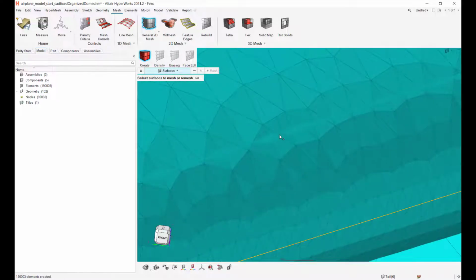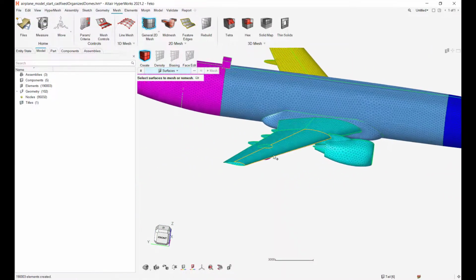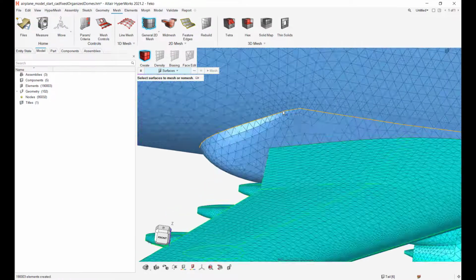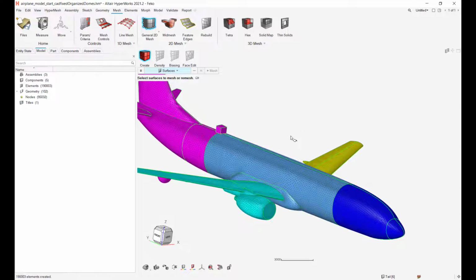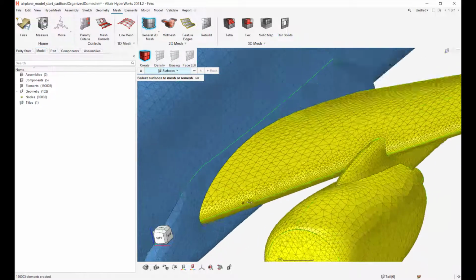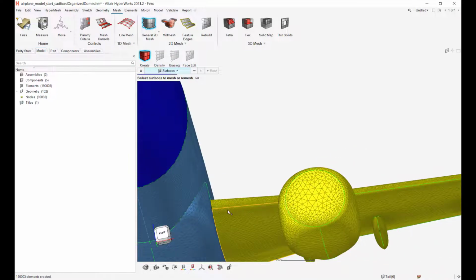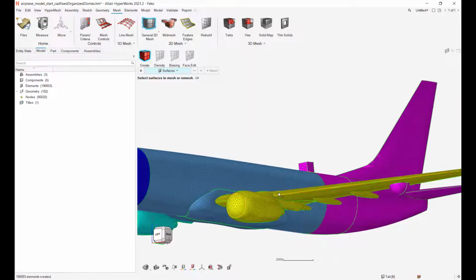okay. So here's some places, right? That is the surface poking out, right? And then we're trying to approximate that with a 2D flat planar element. Okay, so if we stack more in here, we'll get more accurate answers. But I've also heard that FEKO likes a standard element size. So this is where I would revert to the electromagnetics experts in the field. Once again, this is just a button that we can press in order to stack more elements where features are needed. Okay. All without having to do it manually, I suppose, right?